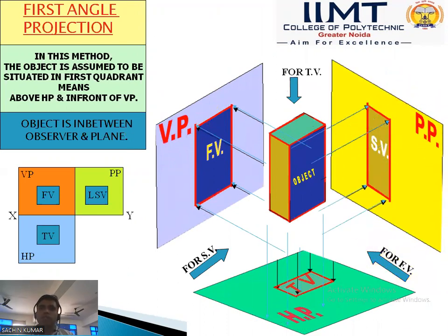So the three different views give the view in the vertical plane, horizontal plane, and profile plane. In the case of the left hand side, you can discuss, we were at the XY line. This object lies in the first quadrant, which means the front view goes above the XY line, we see it in the right hand side and left hand side, and the top view goes below the XY line, and the side view goes above the XY line and to the right hand side of the front view.